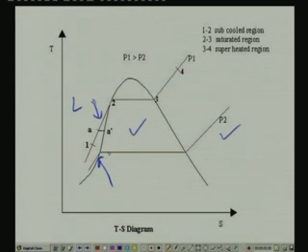And another assumption, which can be shown using thermodynamic relations, is that if you want, let us say, the properties at this point A, which is in the subcooled region, they can be approximated with saturated liquid properties at point A dash. This is one very useful assumption, and most of the time we will be using it. That means if a liquid exists in subcooled condition, and let us say its temperature is 30 degrees centigrade and it is at some pressure, we would like to find out the internal energy and enthalpy at these conditions. So what we can do is, instead of finding the subcooled properties, we can assume them to be equal to the saturated liquid properties at 30 degrees centigrade. So this is one very useful idealization, and we will discuss this when we perform refrigeration calculations.